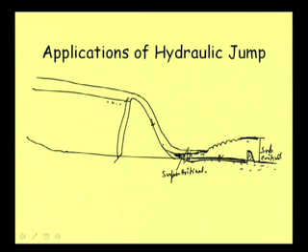Well, and once this hydraulic jump occurs, the energy of flow gets dissipated at this point, and then the downstream portion will remain free of danger. So, it is one application of hydraulic jump.